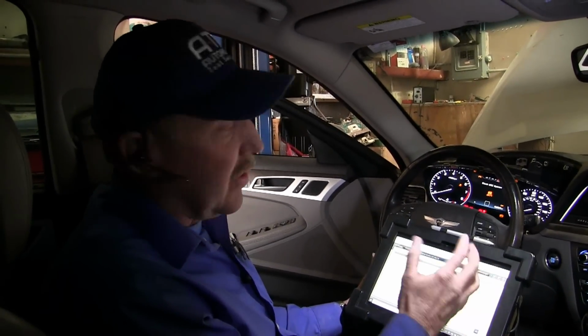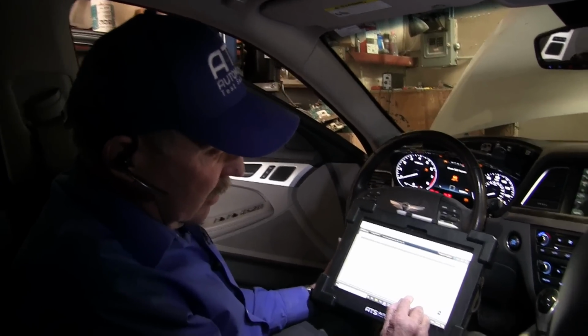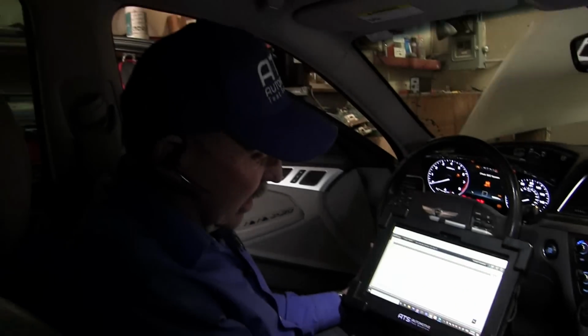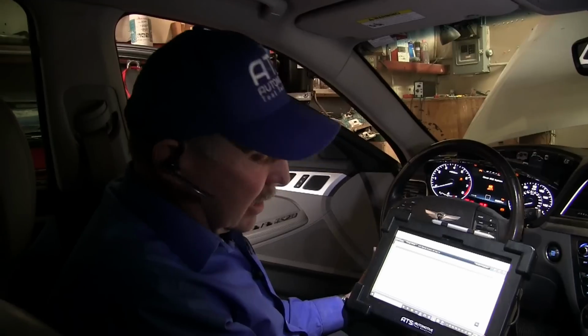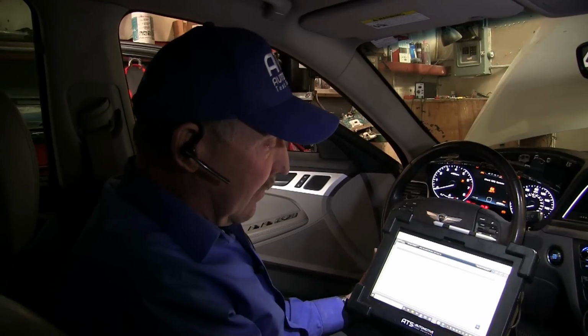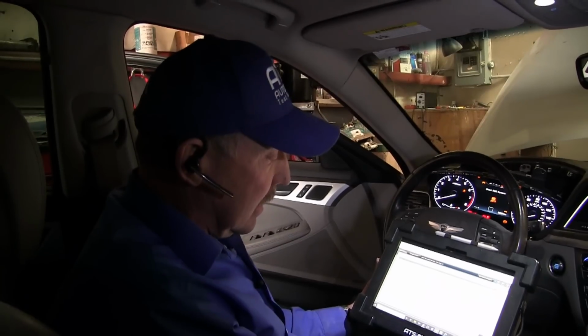but they always put these splice packs where they're accessible. They're somewhere on the car where you can get to them easier than taking everything out of the dash, because I sure don't want to do that until I know which module I'm looking for. So the first thing I'm going to do is I need to go and do a little work, and I need to find out where this connector is. And sometimes to find these connectors is not easy. So let me go see if I can find the connector and see what we can do, and then we're going to take a look at disconnecting it wherever it is on the car, and then we can try to figure out where my problem is on the car.